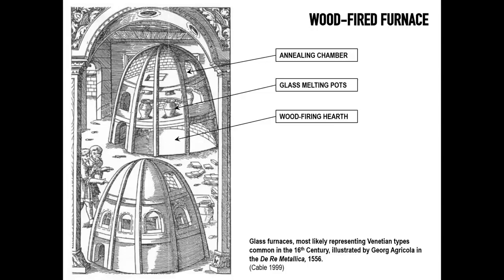Now, glass, as I said, needs extreme temperatures in order to be produced. These temperatures are required to reduce the key ingredients of glass, which are sand, lime, and soda, to a semi-crystalline and liquid, although still fairly viscous, consistency. And the problem with glass making is that in order to have these ingredients mix and combine together to create glass, it is necessary to reach temperatures of approximately 1500 degrees Celsius.